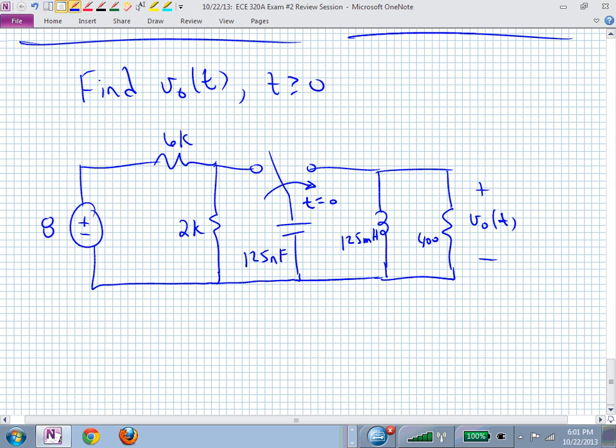Do you have an idea what to do? Okay, so first we probably need to find the initial conditions on the circuit elements. Right now, that switch is over on the left, and what's happening to the current through the inductor? And let's say that switch has been on the left for an infinite amount of time, and an infinite amount of time in electrical engineering could just be 5 time constants. When your time constant's 10 milliseconds, 50 milliseconds. But it's been there a long time. So maybe it's been there for a second.